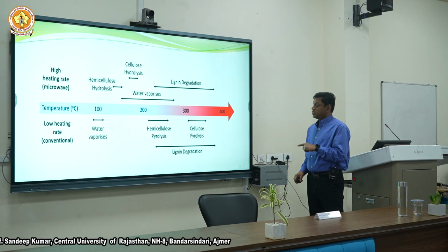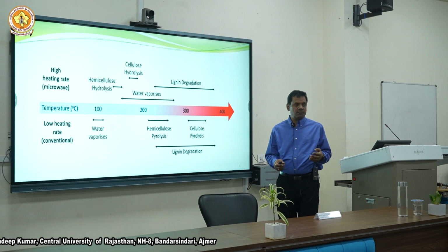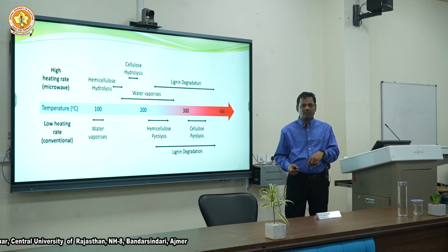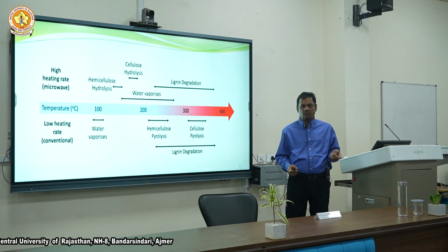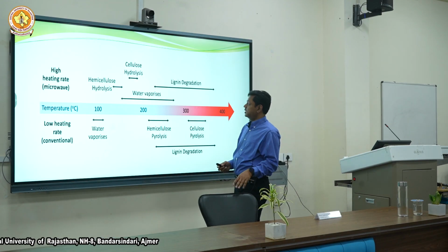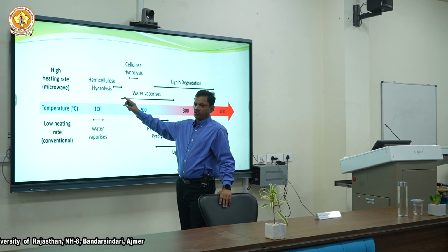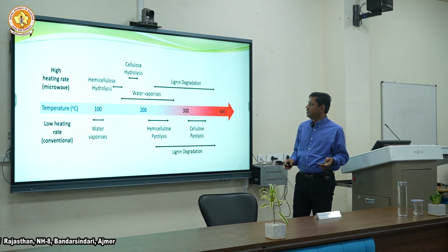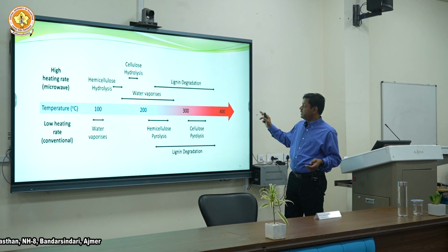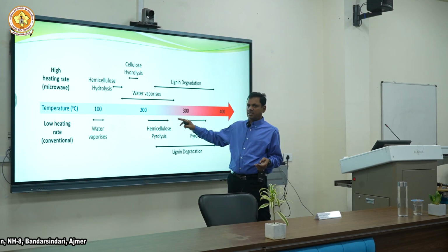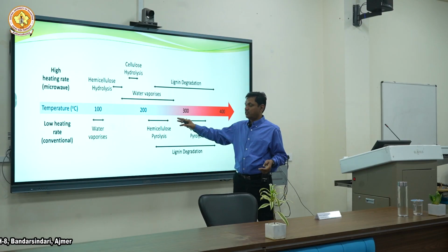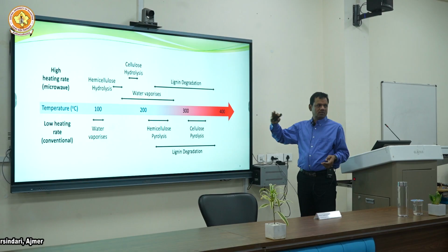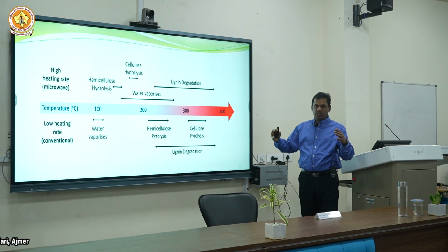Making biochar, what's going on, little details, what was happening: putting biomass and heating it, pyrolysis or hydrothermal, whatever. When heated, typically, as we said, the hemicellulose component will be hydrolyzed at lower temperature, and the water evaporates. Lignin degradation, you will see, yesterday I was looking, is very complex; it starts around 180, 200, and it keeps going. So it's a range band, there is no single point.